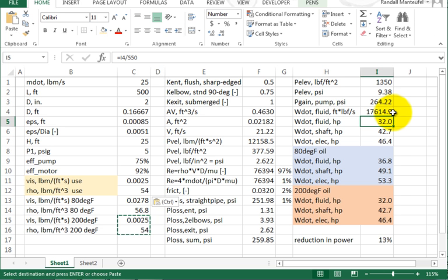And so the warmer oil, sometimes you'll see people, they'll heat up a fluid to reduce the pumping costs on it. Because the pumping costs, if you're just continuously pushing it, may be small compared to heating it up and dropping its viscosity. So it's a significant, there's a 13% reduction in the power if you pumped warm oil versus cool oil.